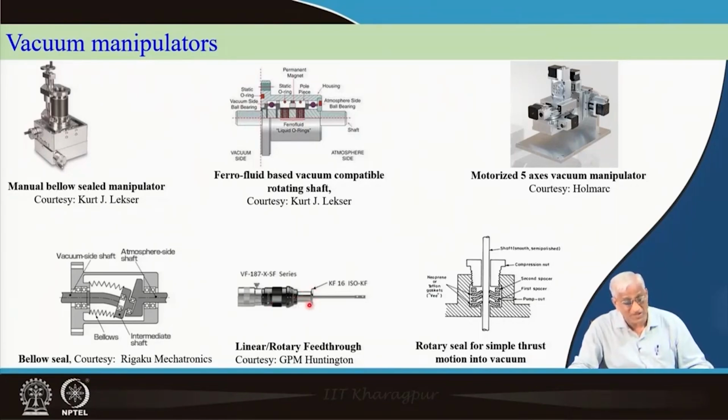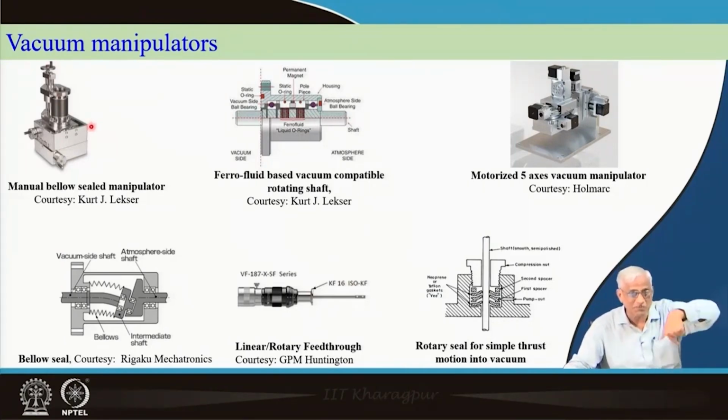At the end there is a flange coupling. So, you can just introduce it to the body of the chamber, that is all, then you can use it as a manipulator. Similarly, these bellows give flexibility, so that whatever manual X, Y, Z motion you are doing, the stem will take the reaction, so that you can shift any material from one place to the other, or move something inside with control from outside.